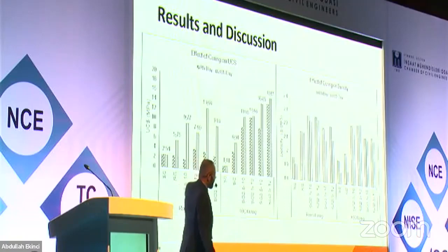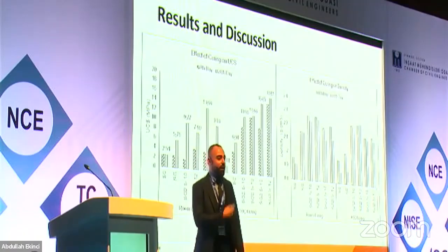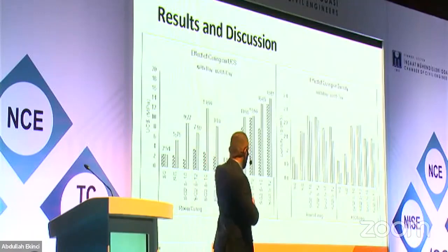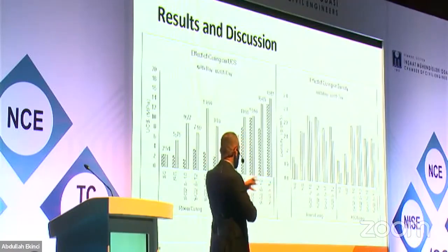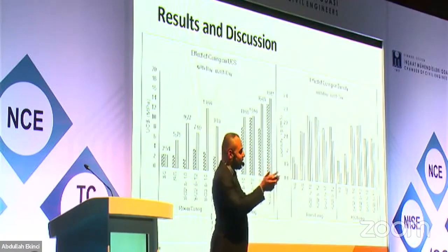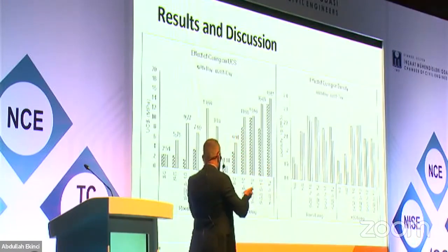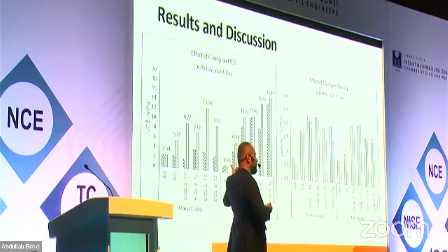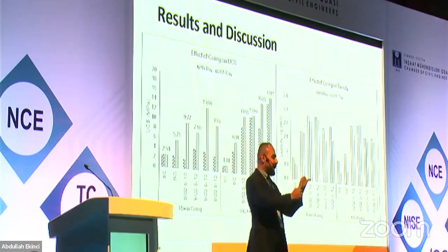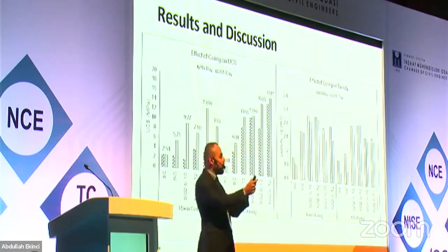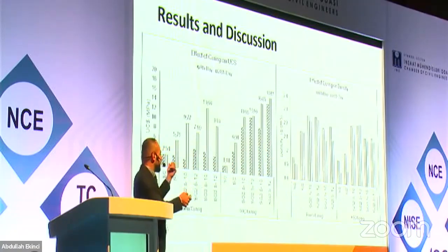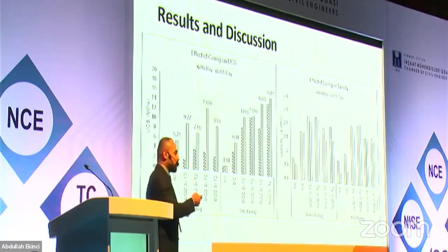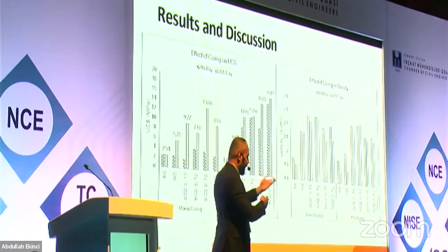However, on the other side, I have it here for the room temperature, 13 megapascal, which is high strength for soil stabilization. That's why we might even shift the idea of this one with a different perspective, not just for soil stabilization, or maybe in future research we will go deeper to look into the porosity, because all of them are compacted. And so we have mechanical and also chemical stabilization. So I might even go for more porosity to see if we can drop this one down with a higher porosity in the future.